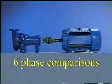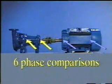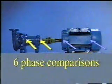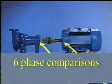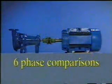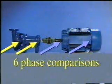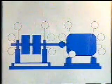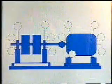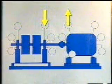There are 6 radial and 6 axial phase comparisons used in diagnosing machinery conditions. The radial comparisons are horizontal to horizontal for each component, vertical to vertical for each component, horizontal to horizontal across the coupling, and vertical to vertical across the coupling. The axial comparisons are from component to component across the coupling, end to end of each component, and side to side for each component. Because there are so many variables, it is sometimes easier to understand the machine's movement when the phase angles are recorded on a sketch of the machine. Then, when making the comparisons, draw arrows to indicate the relative direction of movement.